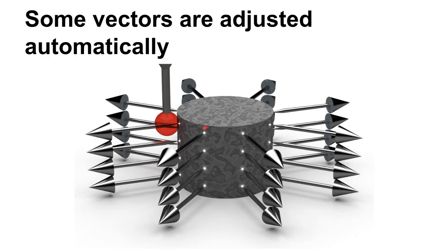And once it realizes that that's a cylinder, it says, well, at this point on the cylinder, the vector must be pointing in this direction, and the CMM will correct all of those vectors and shift the points to where they would be if it was probed perfectly. And so when you probe features like this and you generate features from those points, then that misalignment gets taken care of.